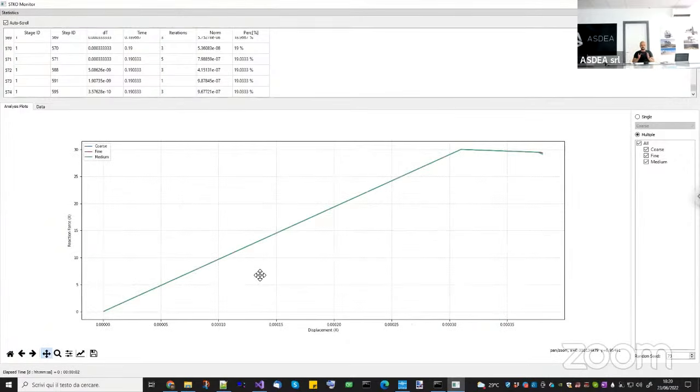So we have a problem of a perfectly uniform distribution of material properties. All the finite elements have the same strength, same stiffness, same everything. But also the kind of problem has a constant state of stress. So you have uniform material parameters and a uniform deformation. So it's very difficult for the numerical method to understand which element should fail, because all of them have the same strength and the same stress.